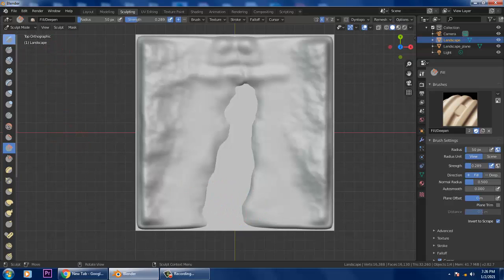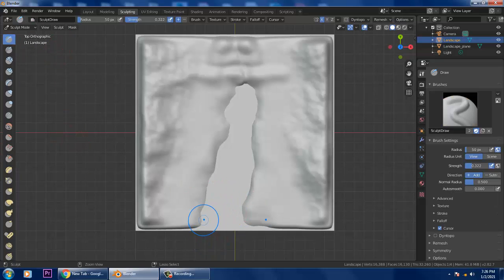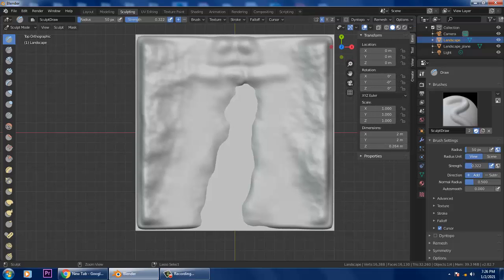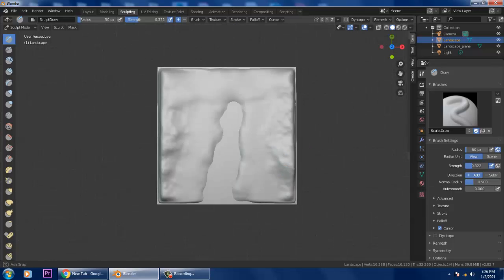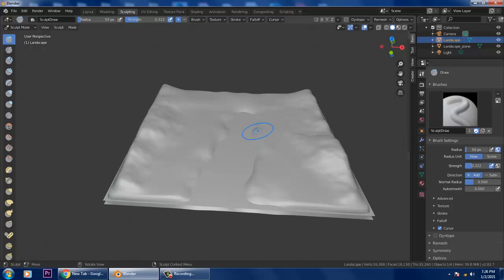Again you can go into the sculpt tool and you have an option over here. If you don't want a mirror on the x-axis, you can turn off that mirror, and if you press Shift, then it is going to smoothen that particular area. So if you want to smoothen the area, you can easily smoothen it there also.